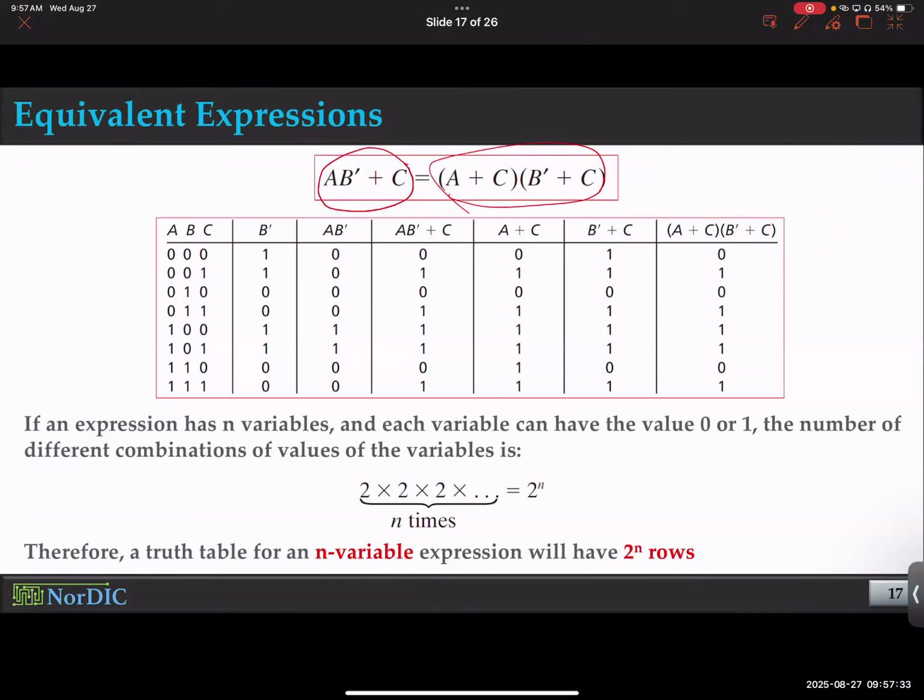Why? I'll show you in the next lecture. You will see the more complex the function looks, the more components you'll need to design the circuit. And remember, every component will take up space, and space is money, right? On a chip, you try to minimize the space as much as possible. Area optimization is one of the biggest things that we need to do.